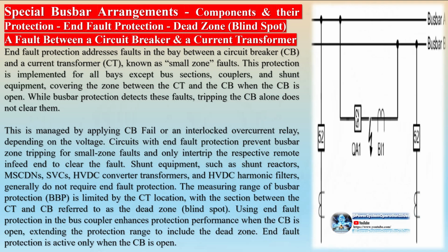Current measurement supervision. This function monitors the differential currents, zone differential currents, and check zone differential currents in real time. If a faulty current is detected, the following actions can be taken: alarm, possibly delayed; full busbar protection blocking, either completely or only for the affected phase; partial zone busbar protection blocking, only for the affected zone and phase. Disconnector position supervision. This function monitors the real-time status of disconnector positions, detecting any incorrect or faulty positions.